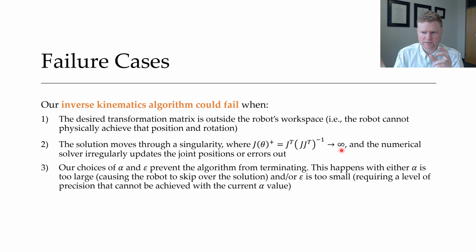that deals with the Jacobian itself. And although it's a numerical problem, it's also a physical problem, because what we're basically saying is, I've got my robot, I want it to move its end effector along some twist V, but because I'm in a singular position, my robot can't achieve that, physically, it cannot achieve that twist. And so that's why you see these sort of spazzes in the robot's motion. It's just something you want to avoid within your numerical inverse kinematics.